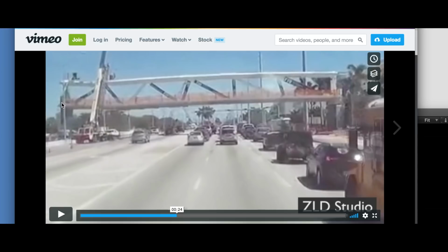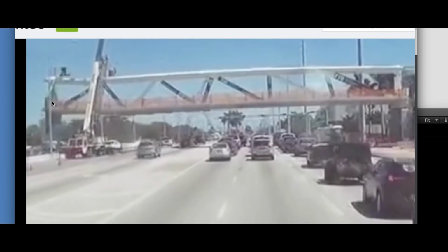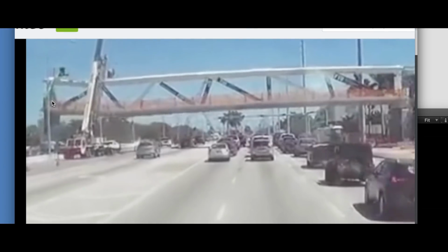This is now the back part of this little nodule back here, which I'll show in part of the video. A little blister, it's already broken off, I think. And we're going to see that 11 has two members in it of post-tensioning bars. One's at the lower half in the deck, and the other one's outside the deck, going through the deck, if you will, and holding on number 12. And I show that as part of his other videos. Let's go ahead and continue.